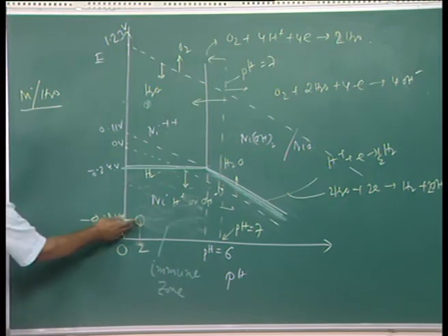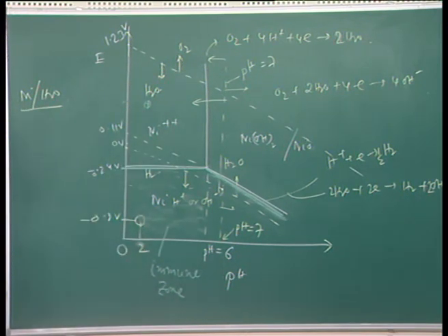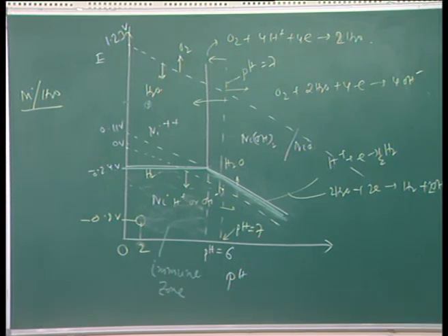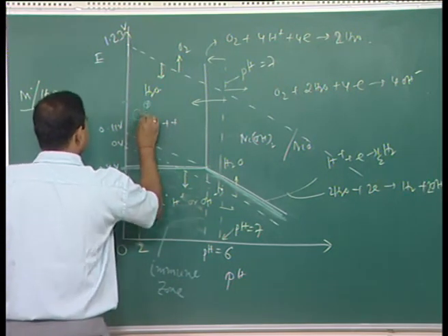The situation here was we have only nickel, no iron, but here we can see that there is nickel ion presence, and that nickel ion is forming from nickel that is dipped in the solution. So, we have the ion formation from nickel, and ion formation is nothing but the dissolution, and the dissolution means its corrosion. So, this zone we call it as corrosion zone.